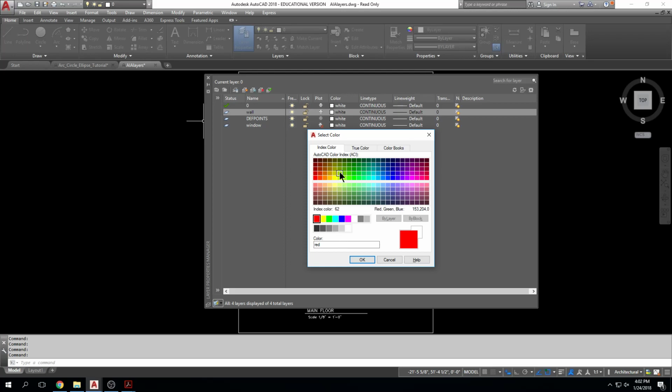They may not know that color number 62 may also be the same line weight as color number 1, red. But people don't inherently know what all of these pen weights are associated with, right? And so it's a safe bet to say, well, we all know what color number 1 is. Make that layer red, make it color number 1. We know it's a thick pen weight. But you're like, hey, but I really like color number 132. And they're like, what does 132 mean? What color is even that? The idea makes sense to them. They know that maybe it's a thick or thin pen weight. And if you tell them it's the same as number 1, they'll say, oh, well, then just use number 1, right? So in order to maintain your standards, it's best just to stay down here, unless you're otherwise told to.